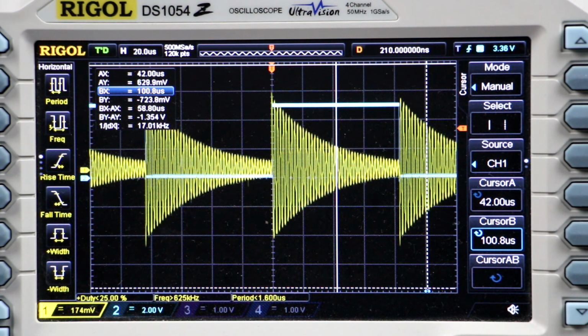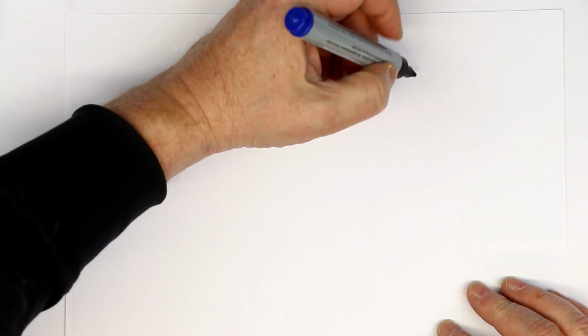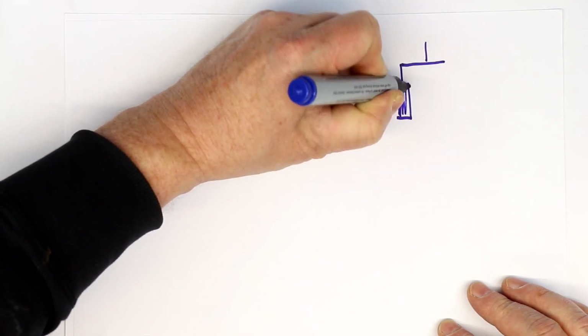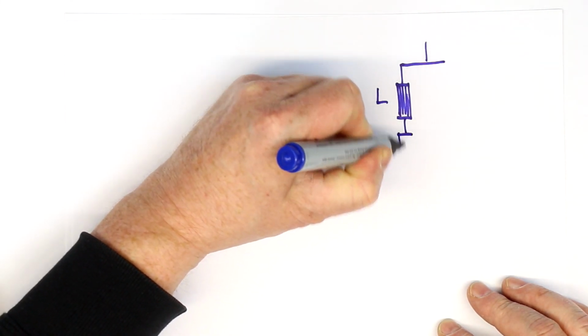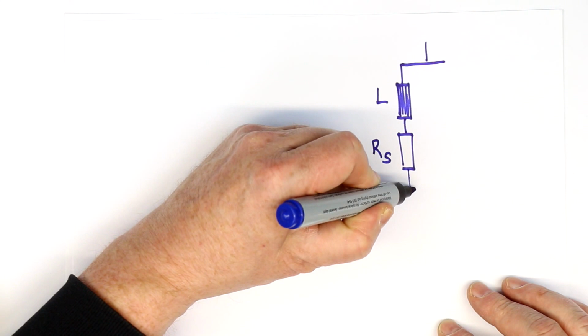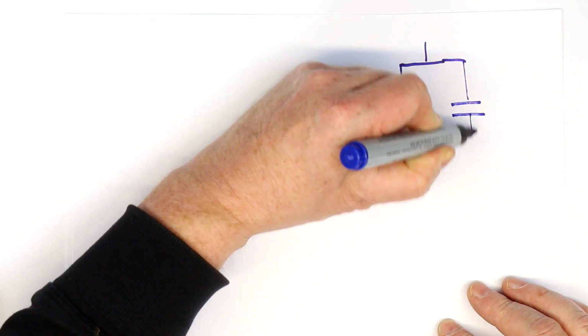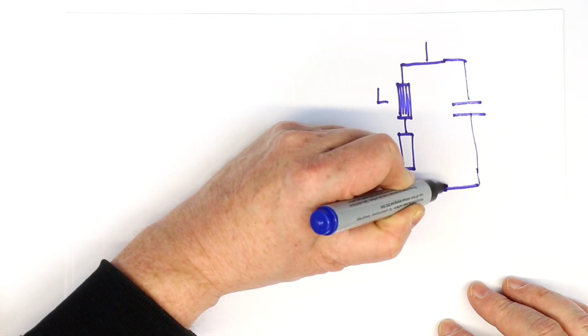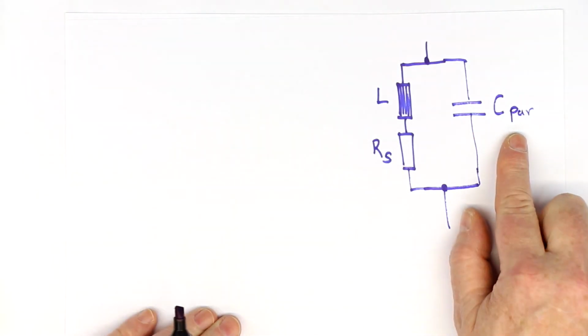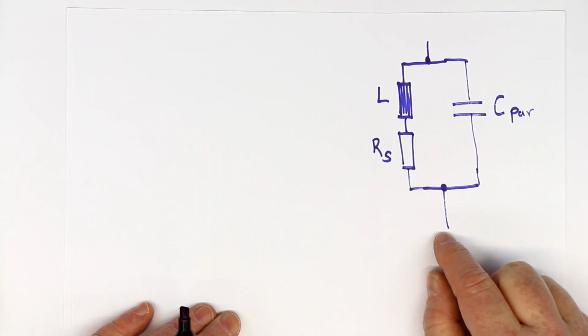And now let's go back to, well, not the blackboard, but a piece of paper, just to do some math to get out the parasitic values of our coil here. So let us for a second recap what we already have. We know that our real inductor does not only consist of its inductance L, but it has a series resistance where the ohmic losses and all other losses are put together. And we have a parallel capacitance, basically due to the winding capacitance, and this is as well parasitic as well as parallel. So that's how our inductor looks like.